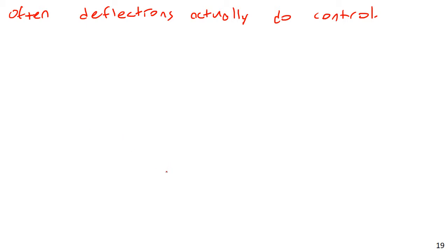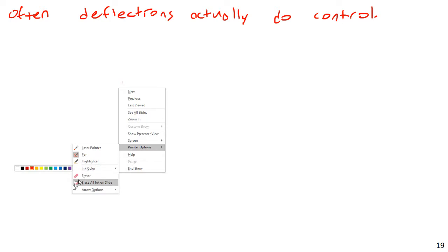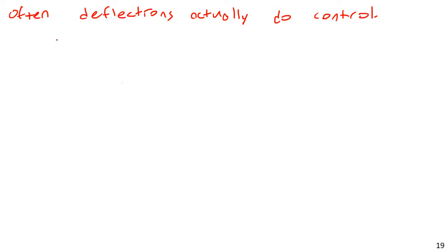When we were looking at the design for moment, we wanted to have tables. It was very useful to have a table where the beams were sorted by the Z, the plastic section modulus. Because the equations for deflection are all in terms of EI, all proportional to this, E is not going to change.